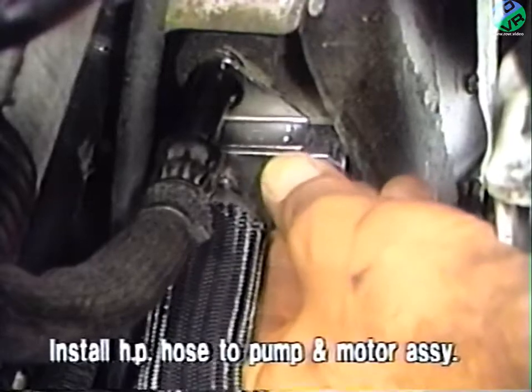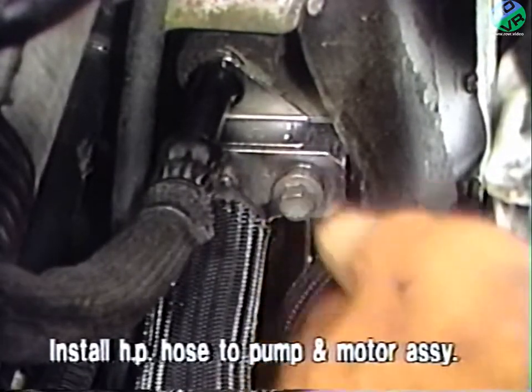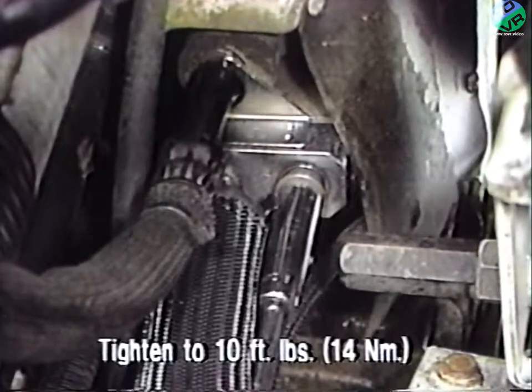Next, install the connector block end of the supplied high-pressure hose to the pump face with the banjo bolt and tighten the bolt to 10 foot-pounds or 14 Newton-meters torque.